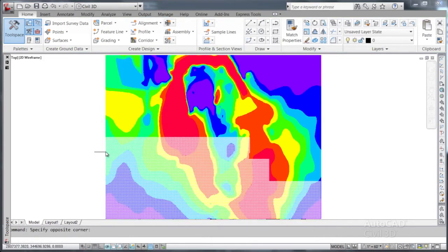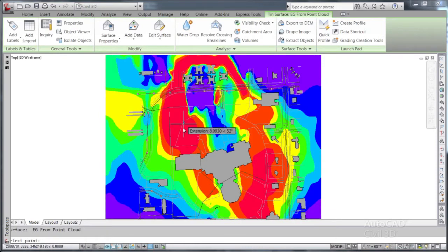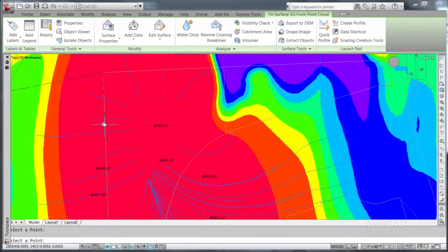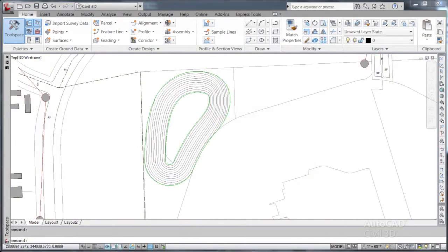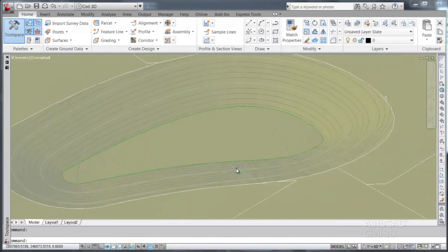Being able to work with the natural environment at the site enables better design that is more economical and reduces environmental impact. The natural undulations identify the potential for a retention pond at the project site to cater for surface water runoff from impermeable built-up surfaces due to car parks and the new wing that is to be built.